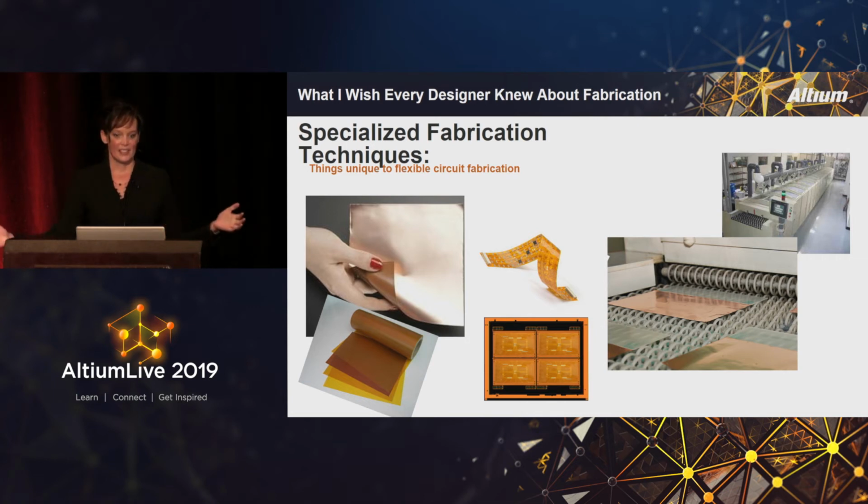So if you can imagine processing an 18 by 24 inch flex panel that's maybe 2 mils thick, a piece of paper, and trying to keep that from getting any dents or dings in that copper at all, because the second that panel drops, it's going to get a little dent or pit in that copper. That's going to be scrap at some point when you create your traces, right? So a lot of work goes into handling and racking and how to put it in trays and things like that. That's one step. The equipment that we use is often conveyorized as well, and those thin flex panels want to get wrapped up in those rollers, right? So fabricators will tape and untape FR4 leader boards to each of those panels prior to running them through some of this equipment.